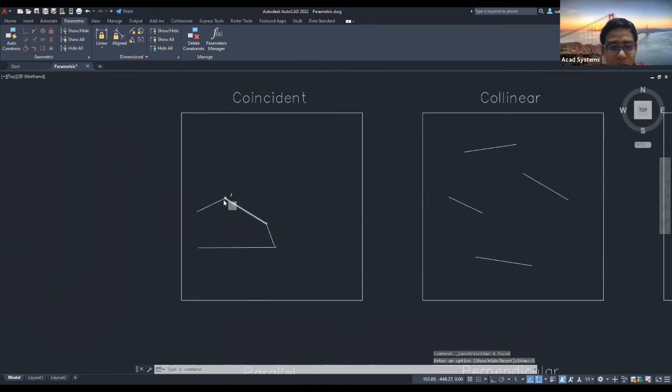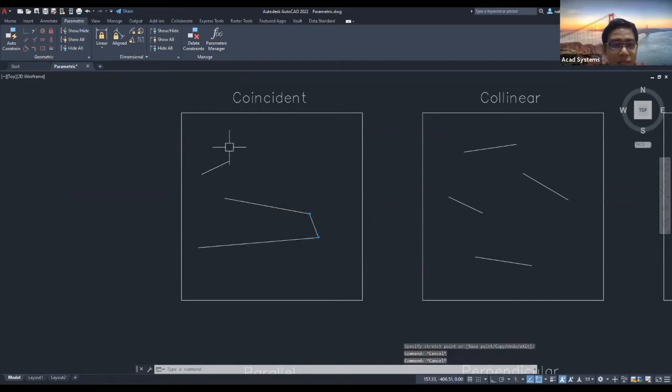Right, so this constraint button. What I can do is go to this icon, right click, and select delete. You can see this blue button has gone, which indicates the constraint has been deleted from over there. Now if I want to delete more easily, I can also use the manage tab. I have delete constraints, which I can simply use from the selection box, and it has been deleted.